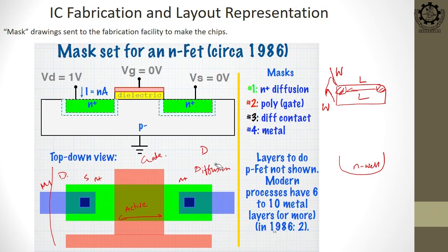Now, are we forgetting anything? Gate is done, source is done, drain is done. Are we forgetting anything? Substrate, because it is the fourth terminal, there are 4 terminals. So, substrate for NMOS, it is common for all. Suppose you have one NMOS here, another NMOS here, another NMOS here, but the P substrate is the common wafer, still we need to give local connections for all of these substrates, getting my point.